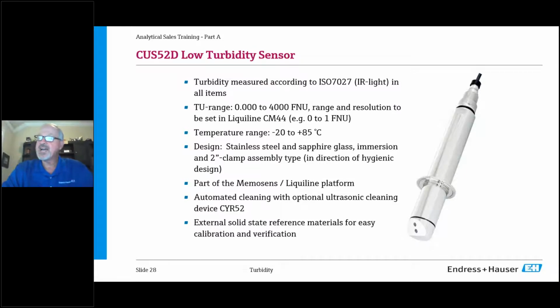You will oftentimes hear turbidity units referred to as milligrams per liter, NTUs, FTUs, TUs. All of them mean the same thing. They all are scaled the same. They all mean the same. They just use a different standard to make the calibration, and it makes no difference as to what you refer to it. Nephelometric turbidity units is the typical standard.